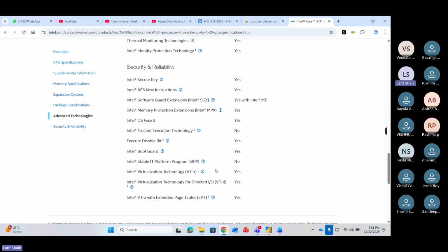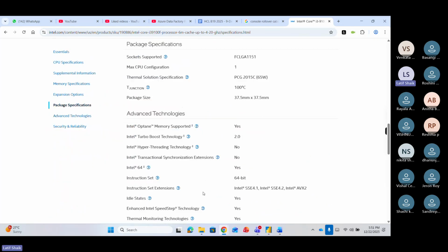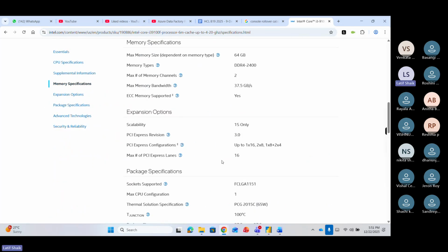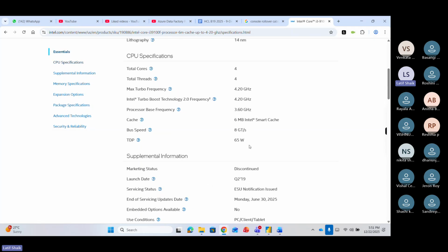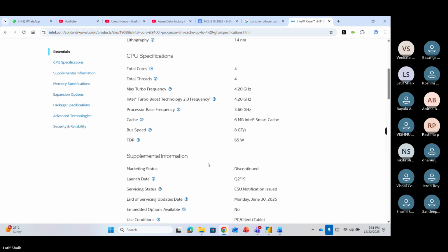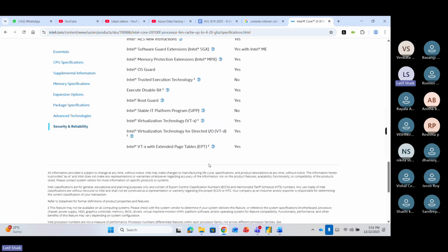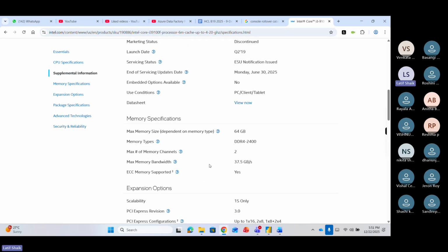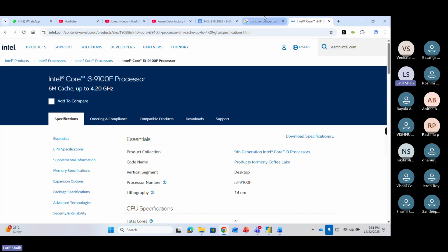Okay, graphic memory is discrete. So you can see there is no graphical memory information showing. RAM is showing, everything is showing, but no graphical memory. It is specified that time that a discrete graphic card is required. Okay, so obviously I purchased another 2 GB graphic card, inserted it and it is working.